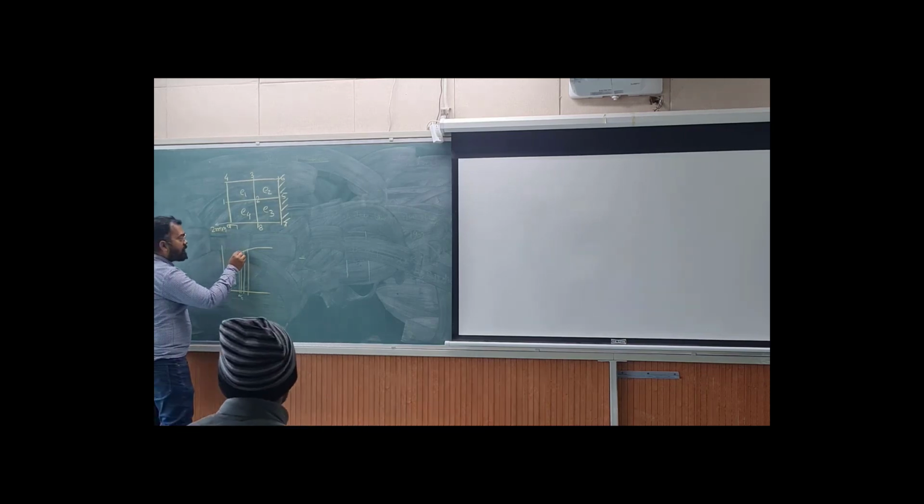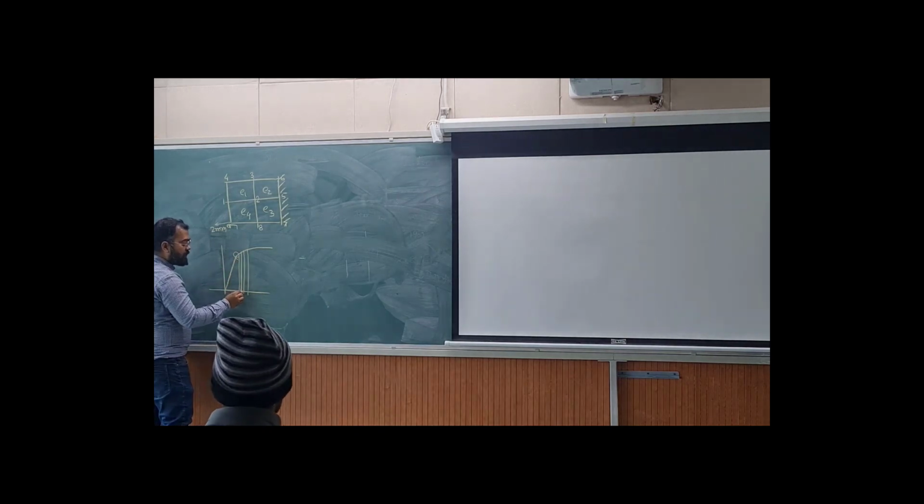Suppose the yield strength is crossed after a displacement of 1 millimeter, and I am doing it in one step, so I have applied the whole 2 millimeter. That means it is in the plastic region now. After the plastic region, it has only one point for calculation because I am applying it in one step, so it is going to get one value of stress.